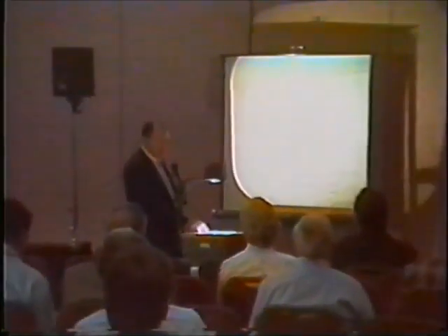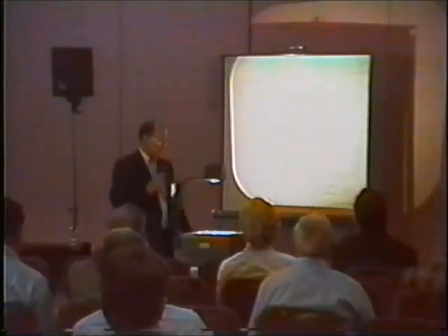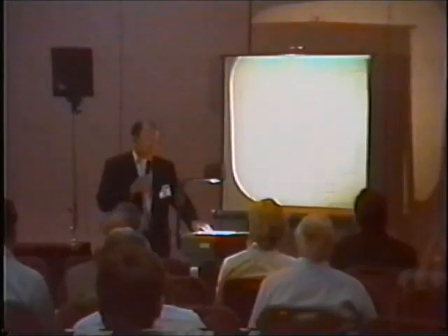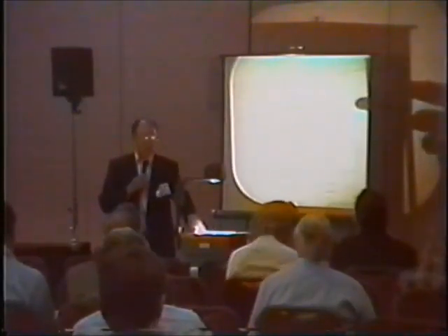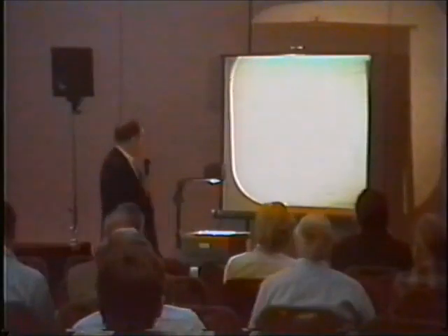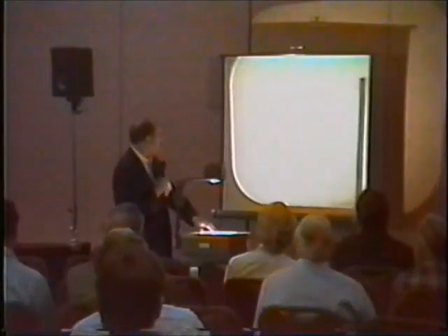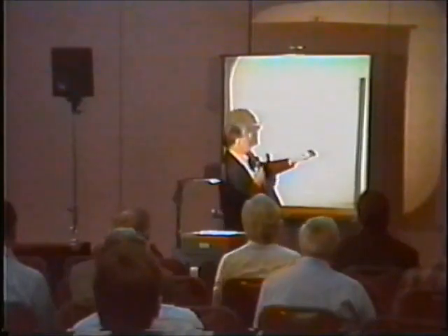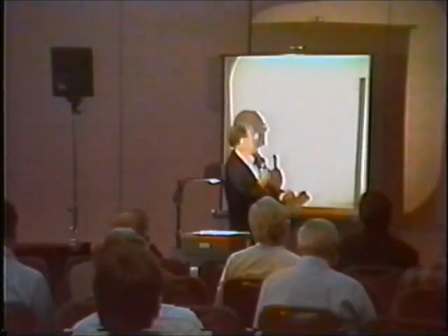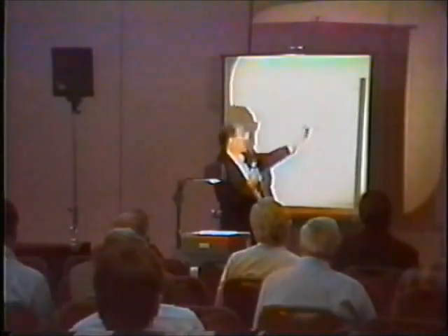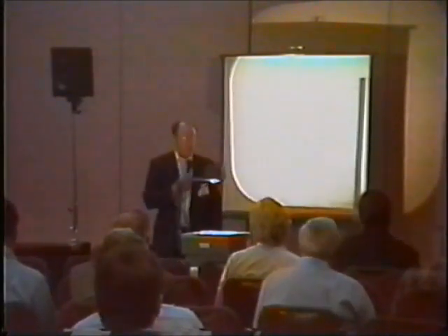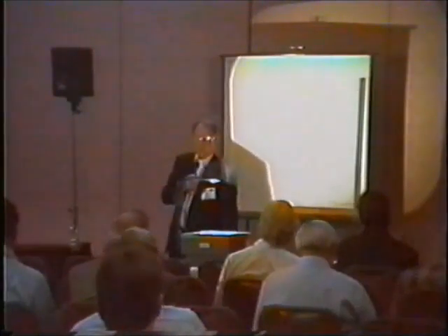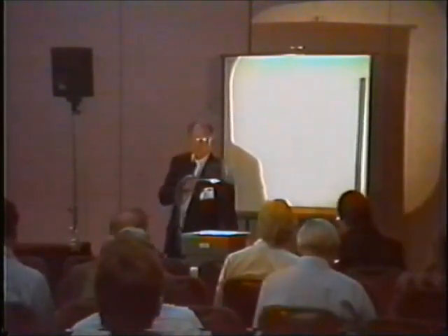Okay, several of you wanted to see that circuit for the Marx generator. There's a German fellow who came up with this back before the war. The basic circuit is in the upper right-hand corner, and it consists of one of those spark gaps that we were looking at, a capacitor, and resistors and other capacitors so as to control the level of energy and direct it so that most of it goes in one direction.